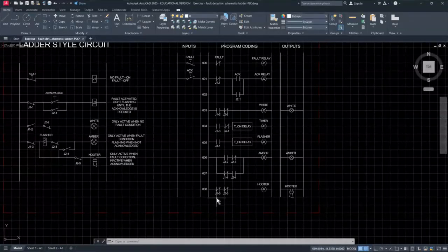And there is no PLC which could not handle 10 or 20 contacts. They can handle hundreds, which means it doesn't actually cost you anything. You can simplify your program by adding extra contacts in. There's no need to optimize it unless you're working on something which is really big and your PLC does not have enough contacts, so you can utilize them.